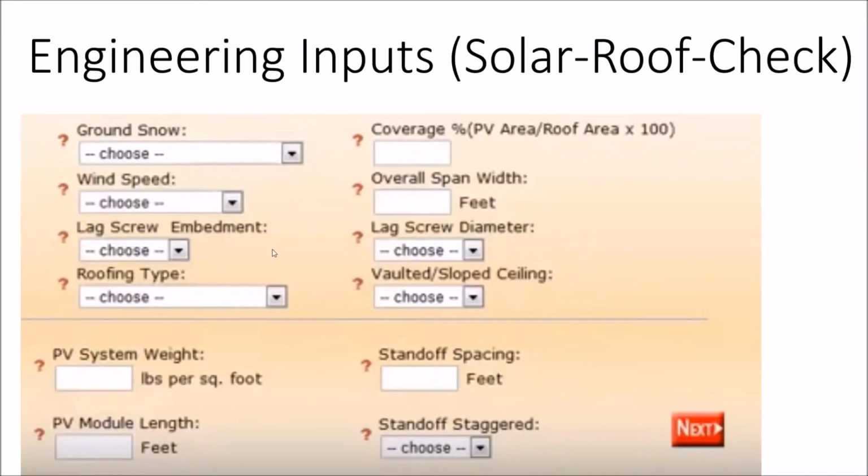To finish off our structural engineering discussion, I try to encourage the client to get engineering stamps on all the projects, but I'm not a professional structural engineer. I can't stamp structural documents, but I've found even online there are engineering companies specializing in, say, residential structural stamping, where just like the racking companies, you're putting in your snow load, your wind speed, your array information, but they say, okay, but what lag screw are you using? What's the diameter of the screw?